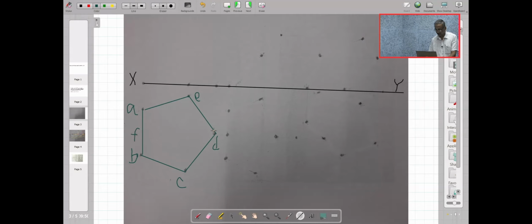Here again I can join the line connecting the midpoint to the opposite corner. So this is the line FD. I am having more interest towards the line FD because the line FD has to make an angle of 30 degrees to VP. Now this is my top view. Let me draw the front view.